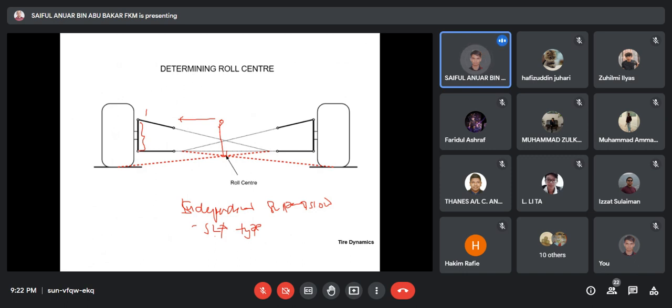Because in the end your shock absorber is going to hold your chassis, right? So you need to lower your chassis, like in the typical modification we go through. You cut your spring, or you use a shorter stroke spring and shock absorber to lower down the CG. Okay, this is the only option. But if you want to lower this arm or this knuckle length, you need to do it at the beginning of the design phase of the vehicle.